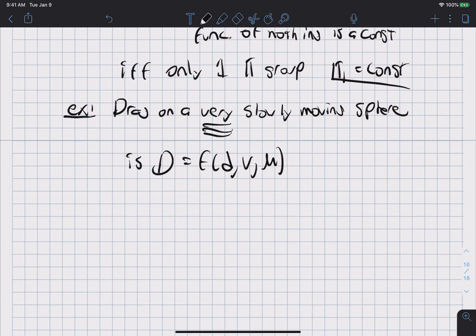In this regime, it's called creeping flow. Here the streamlines actually hug the object for the entire way around, but this only occurs for extremely slow moving flows. For everyday objects, you almost never have creeping flow. But if you have an extremely tiny particle, on the order of 1 or 10 micrometers, it's very easy to have creeping flow conditions.